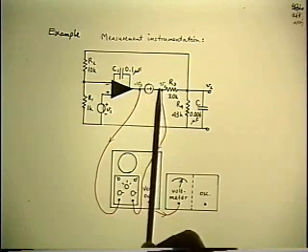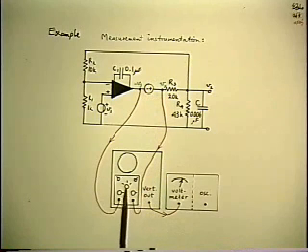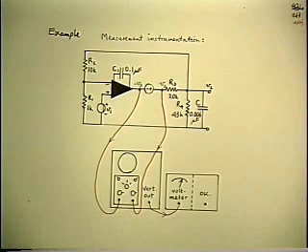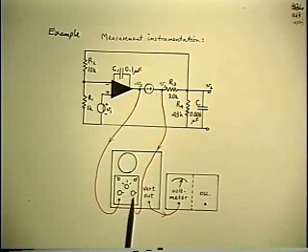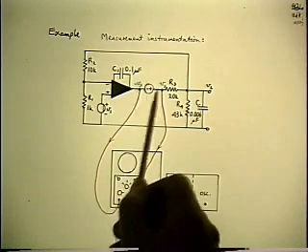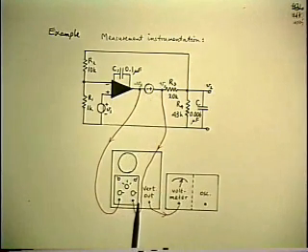But it's the phasor sum of these two. And there's another knob on the front of the dual channel preamp that says sum or difference. Or maybe it only says difference, but there's another knob that says invert. So a combination of the two allows you to make a choice of whether you read the sum or the difference of those two waveforms.